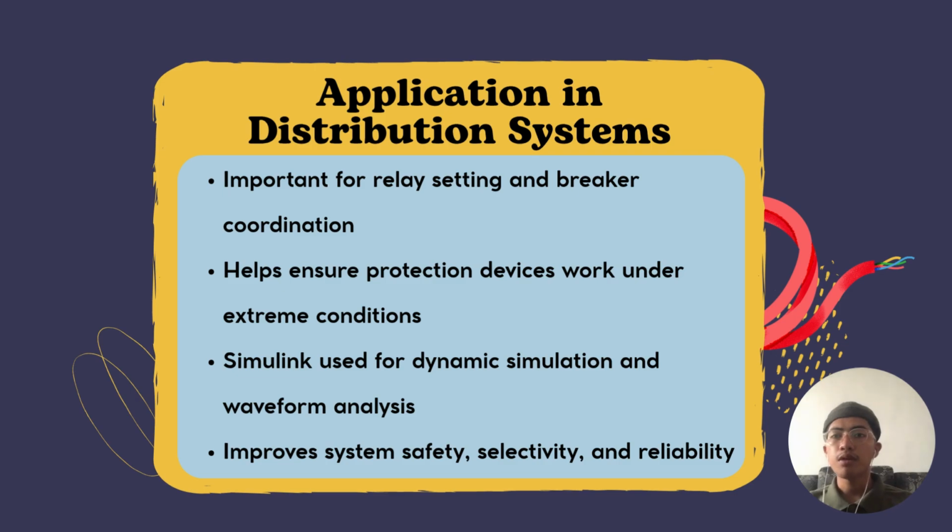And lastly, for the literature review, is application in distribution systems. Although more common in transmission networks, balanced fault analysis is very useful in distribution systems as well. It helps engineers determine maximum fault current, ensure proper relay coordination, and test system response under critical conditions. Using MATLAB Simulink, we model the fault and study how protection devices respond, making sure the system remains stable and safe.